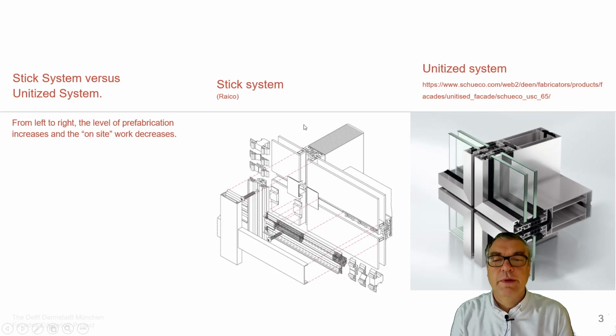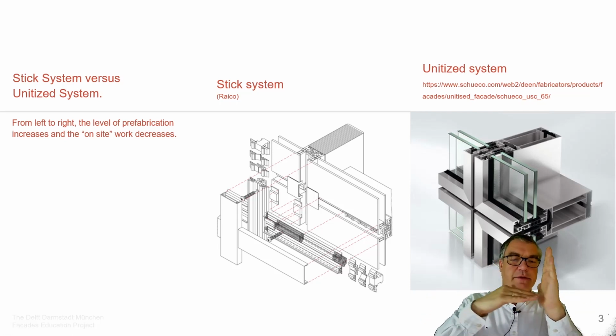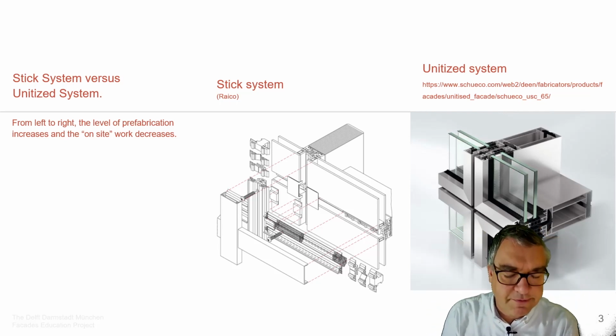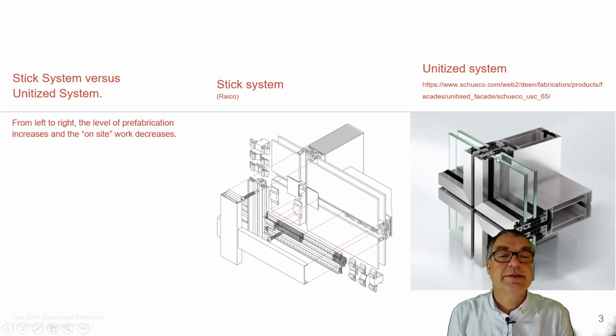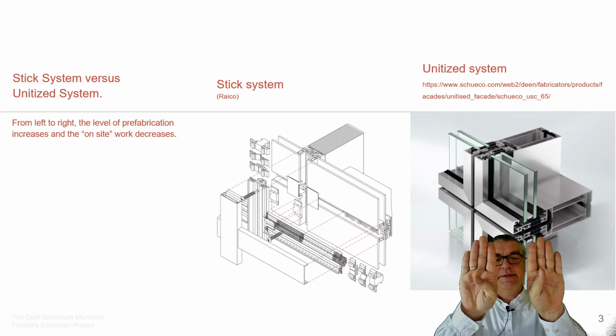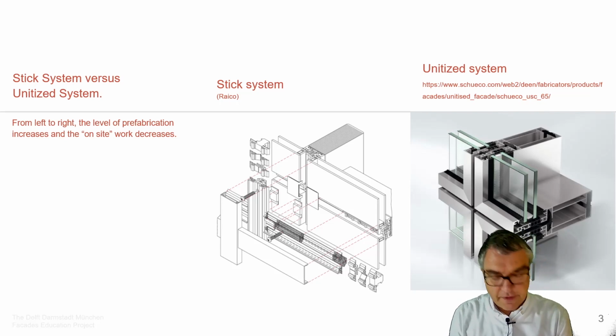The sealant inside versus outside needs to happen at this situation where the glass and the stick are actually connected, versus the unitized system where we do not install sticks and horizontal rails, but entire frames which are already enclosed with the glass. So the sealant of the glass has to happen directly to the frame, and then the frames themselves have to be connected to each other with sealant, so that each frame, being already tight, is connected to the next one to get a sealant in between the frames. We see 3 layers of this sealant, which is what we do with prefab systems.